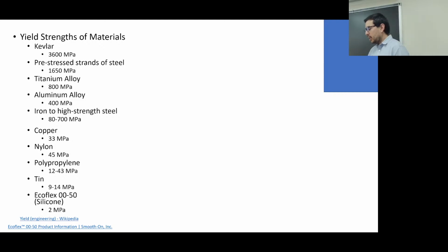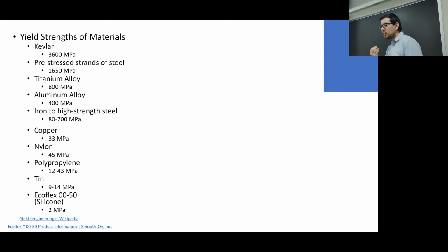Steel, as we mentioned before, can come in different compositions, but its elastic modulus stays the same, as we also mentioned before. What I didn't mention too much is that the ways that you can change the yield strength are often synergistic with where the maximum stresses are going to occur.